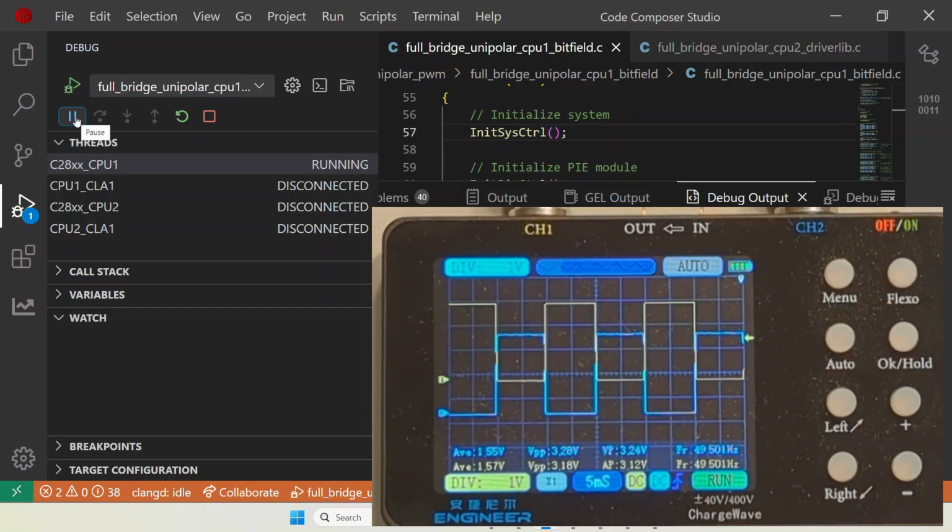So this clearly shows that because I have chosen 50 Hz to be the frequency of the phase angle and therefore of the modulation signal, our S1 and S2 are now operating at 50 Hz frequency. Which means that S1 remains on for the entire positive half cycle of the modulation signal and S2 remains on for the entire negative half cycle of the modulation signal.